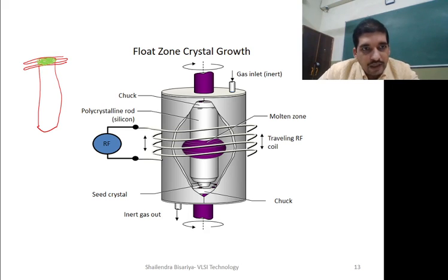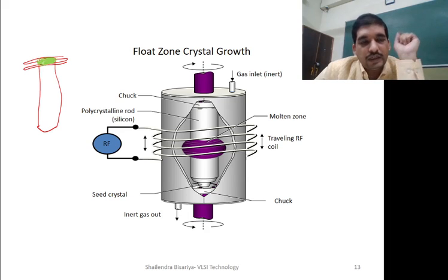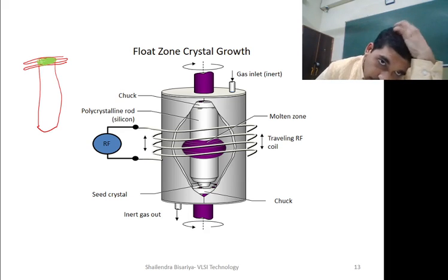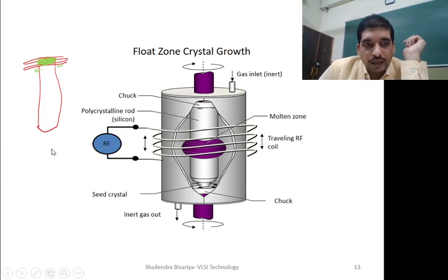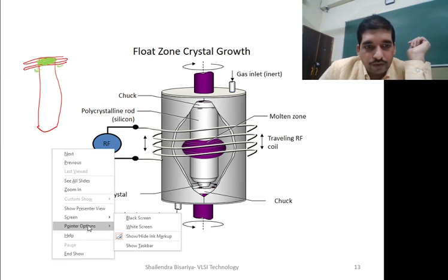And when this area is melted a bit, not completely, the interesting property is that impurities move away from the heated area. Because of this feature, impurities will move away downwards. Now in the next stage we will move the position of this coil.